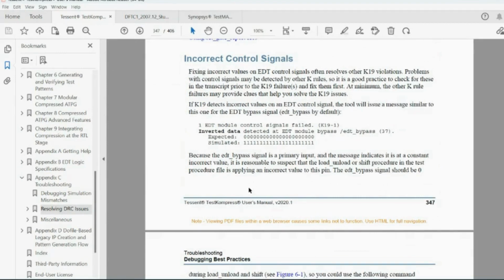You're working on a post-placement and routing netlist given by the PD team. They have added some additional logic or additional cells or changed the existing scan chain order. Scan chain order can be changed only by the physical design team for the purpose of placement.